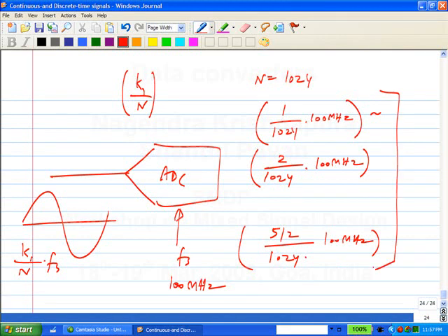Okay, but if you arbitrarily set the signal generator to some value, it could be at, let's say, 3112.5 by 1024. Then you will certainly get signal leakage and you will not be able to distinguish things correctly. So when you are measuring A to D converters, this is an important thing. Also when you are simulating, because in fact the simulation is a bigger problem. You can't simulate for as many points, right?